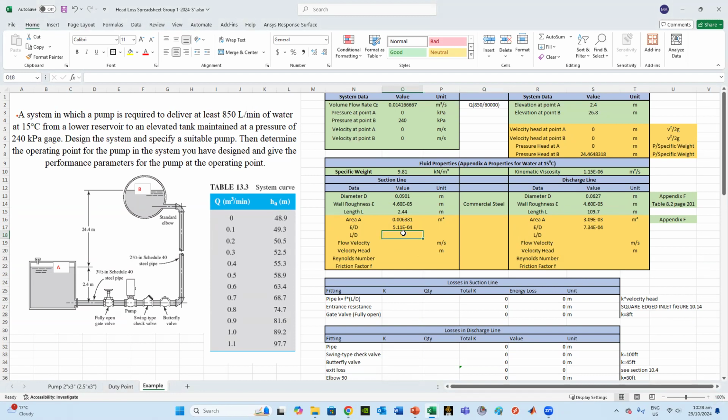The other information, which is a ratio as well, will help me with the Darcy equation. That one will help me to calculate the Reynolds number and the friction factor. Then this one will be the length we assume divided by the diameter. Make sure that's why I have the same units. And here will be equals the length divided by the diameter.